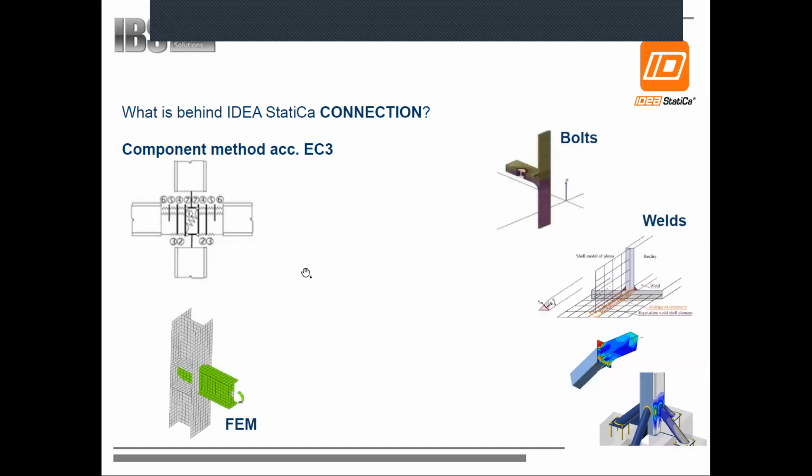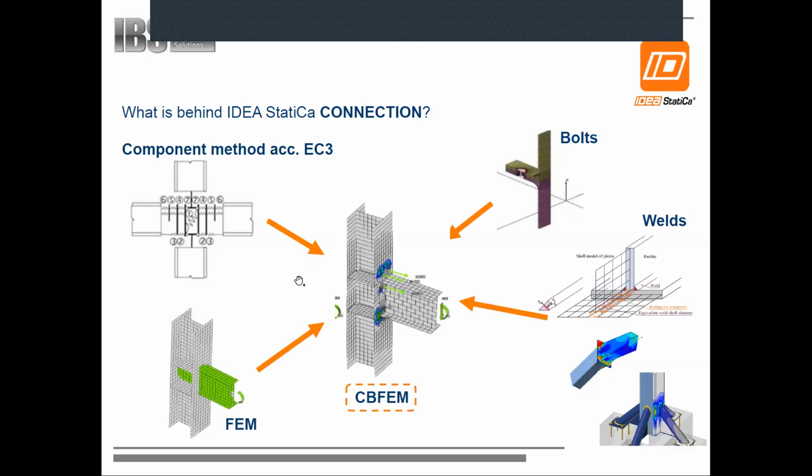In Eurocode 3, in the steel Eurocode, there is a methodology for how to calculate steel connections. And IDEA Statica uses this component method, and together with the finite element method and innovative models for bolts and welds, combines everything together in one new method, so-called CBFEM. This CBFEM method can be translated as component-based finite element method, so it's quite easy to remember.